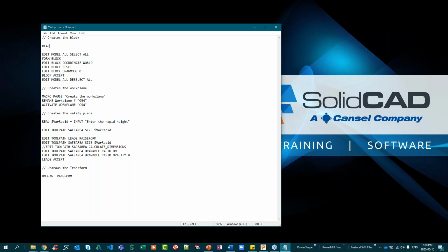There's a better breakdown of what each one of these represents in the macro programming guide. So again, go up to the help menu, inside resources, there's an option there for the macro programming guide. It'll give you a breakdown of what each one of these represents. So real, it could be a number from 0.00001 all the way up to, I think it's 16 digits if I remember correctly. So you can put any value in there, where an int, which is an integer, has to be a full value, like 1, 2, 3, 4, 5. So that's why I'm using real. And then I'm going to establish the variable, using VAR for variable, so I know exactly what this is. I'm going to put variable X and maybe just len for length.